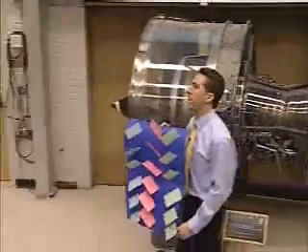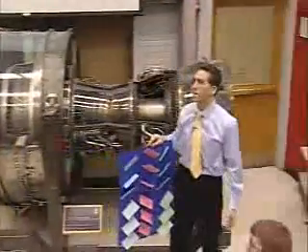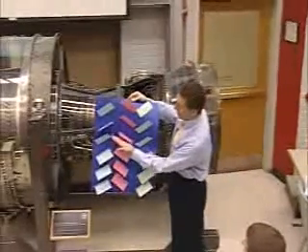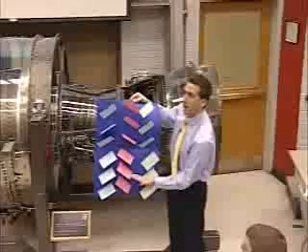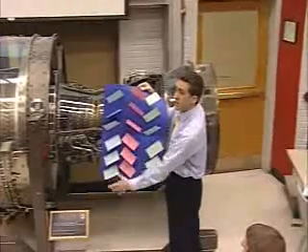Yes? In that problem, aren't we saying that the streamlines are coming in at an angle, because you would have velocity vectors coming at an angle, but it would just be coming straight through? It could be, but it turns out that if you have a lot of vanes, the flow tends to follow the vanes. So that problem is a stator. It's just a fixed set of vanes.